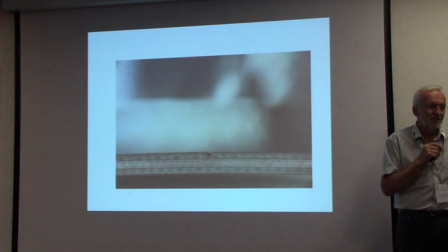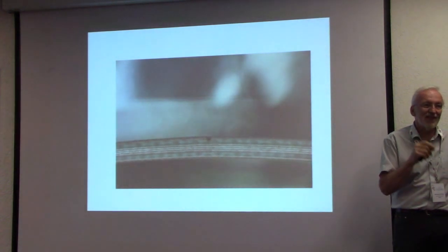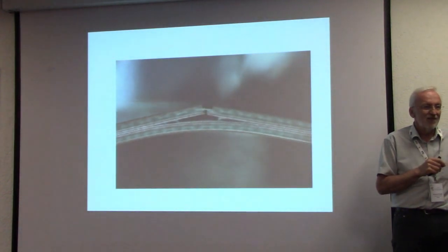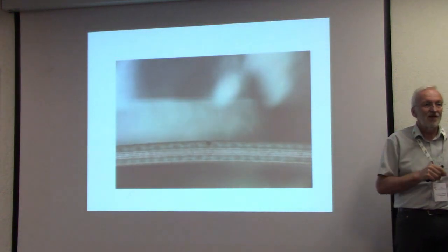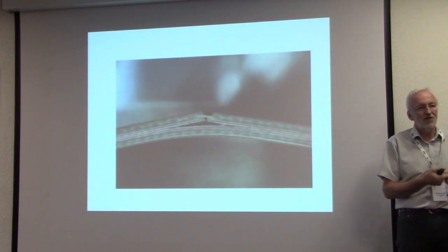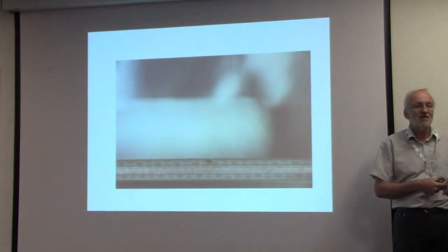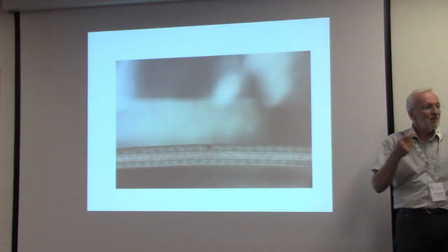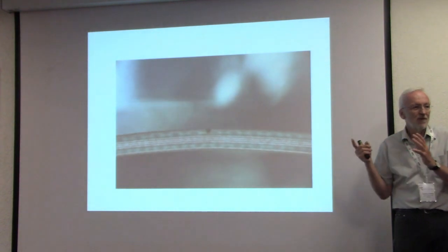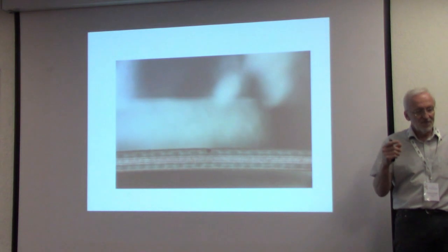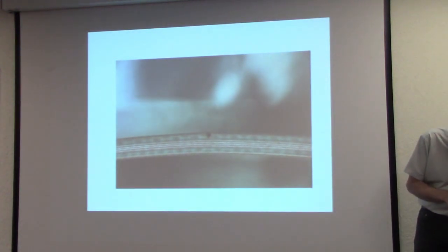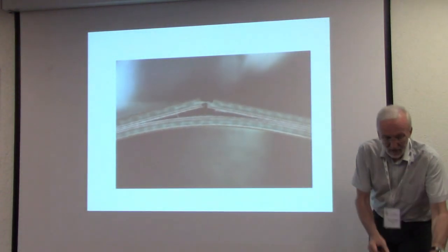ideal brittle case. If it is not an ideal brittle case, it becomes really not easy, and it is always then not a single value of the interface toughness, it is then always size dependent. Similar to what we have seen before. When plasticity is involved, then we have a size dependence of these phenomena.